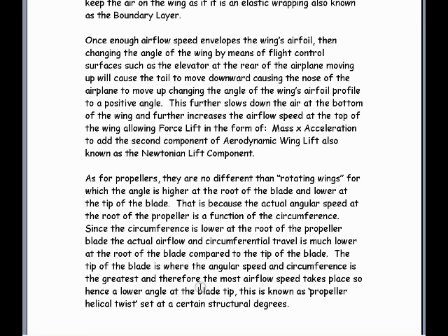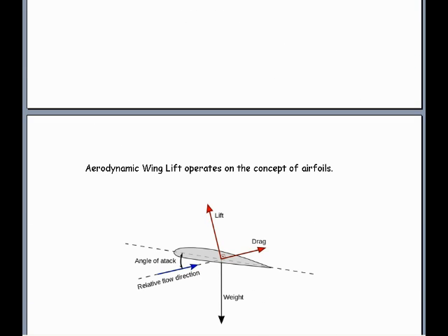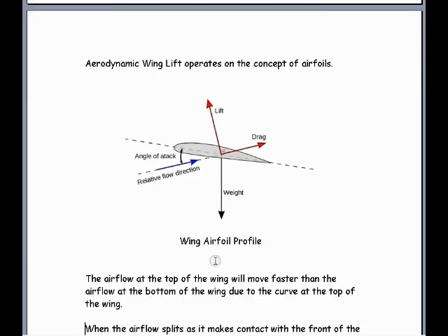As for that force representing the thrust, or the lift, that's what you're getting out of it. So as you can see, there are two different vectors that come out: one for pressure lift this way, and one for mass acceleration that way, so the resultant is a lift kind of in between that. That's just the vector sum.